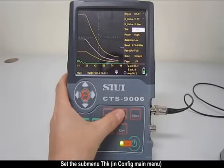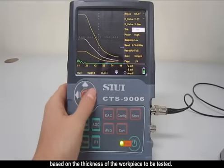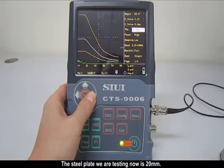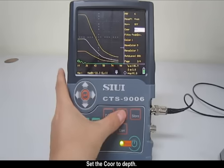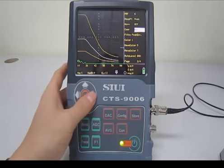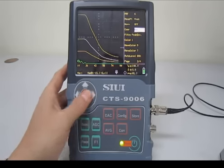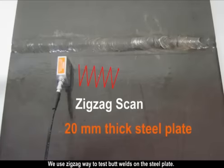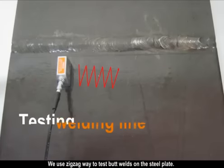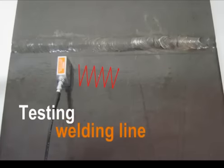Set the submenu thickness in Configure main menu based on the thickness of the workpiece to be tested. The steel plate we are testing now is 20 mm. Set the coordinate mode to depth. We use zigzag way to test spot welds on the steel plate.